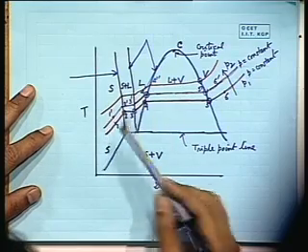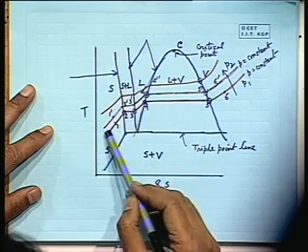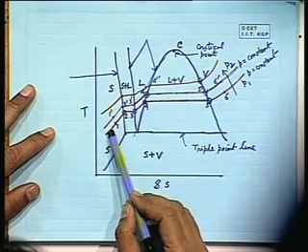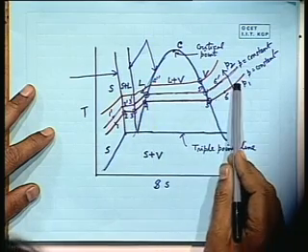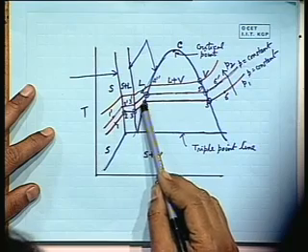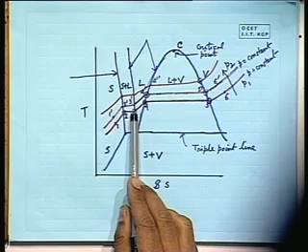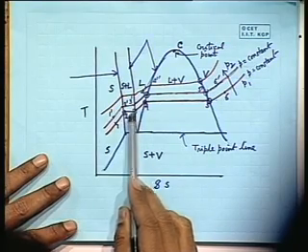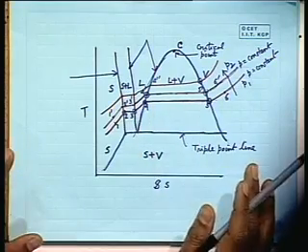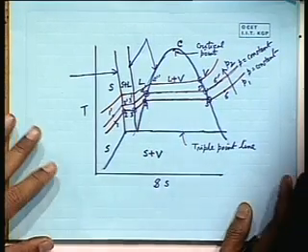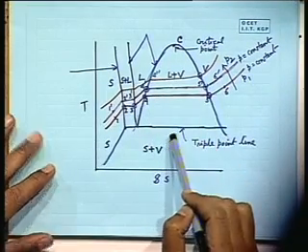And these red lines are the constant pressure lines. One thing we have appreciated is that a constant pressure line looks like this, that means at constant pressure, if temperature increases, entropy increases during the sensible heating part of a substance. This is the vapor phase, the gas phase, this is the liquid phase, this is the solid phase. While in the course of phase change, both pressure and temperature remain constant. So a constant pressure line runs parallel to the s-axis, because T is the ordinate, that means it becomes constant temperature also. And similarly, this is the triple point line, which will come afterwards. This is the figure for the phase diagram in the TS plot.